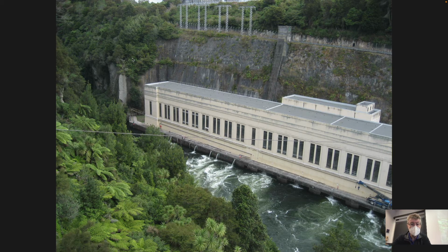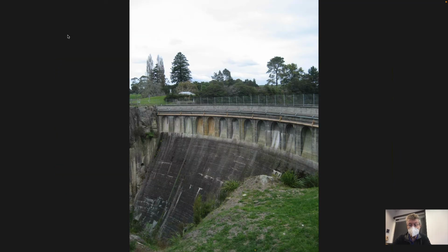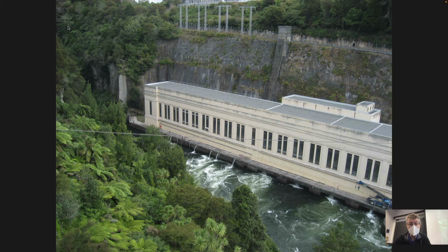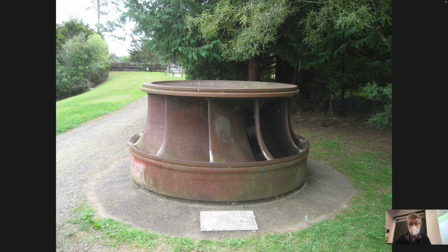So this particular dam, the river would come in from the left downstream. Actually, it's dammed. The dam you just saw is to the left in this figure, upstream. It takes all the water and it shunts it into a canal, which is back here. And then once shunted in the canal, it comes through the back of this scarp into the transformer hole, where it's generated into electricity and then discharged into the original riverbed and then cast downstream to the next dam, which collects it. A defunct turbine.